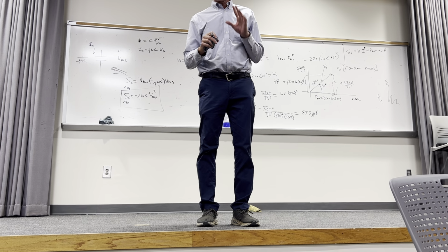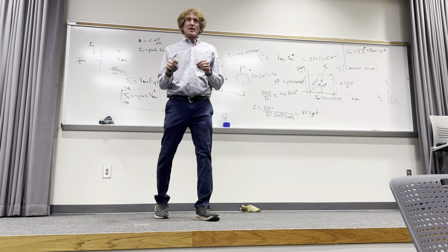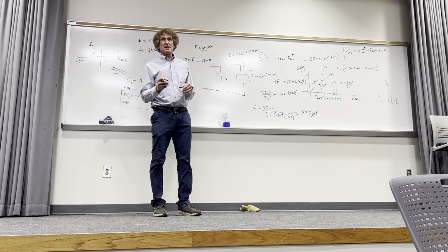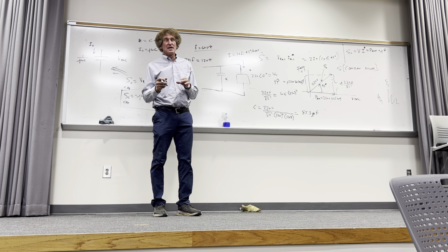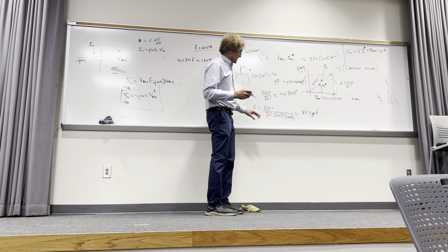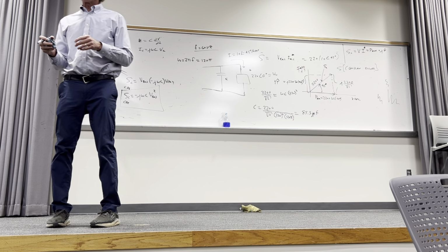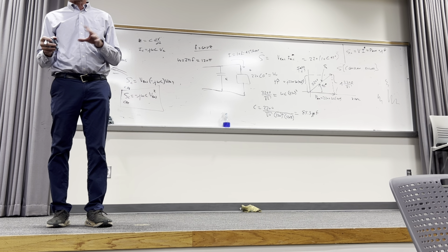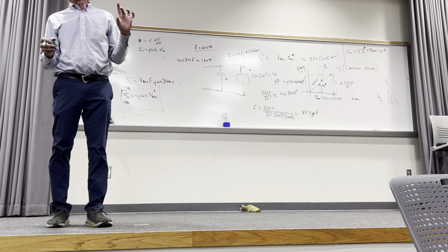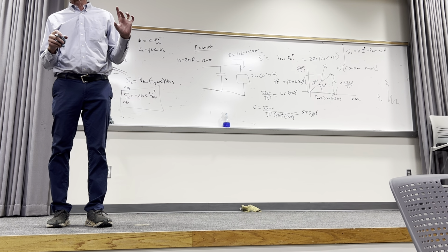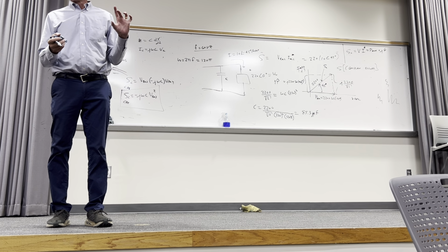That's reasonable. Let me say one thing about this. Some of you may be working in industry, and you're going to have to make decisions on it. The value of the capacitor is one thing; that's a very easily achieved value. But in industry, you want to make sure your capacitor is rated for a breakdown voltage that it can't exceed. Make sure your capacitor has at least double the RMS voltage on the line. Here it's 220, so you would want something that could withstand at least 440 volts.